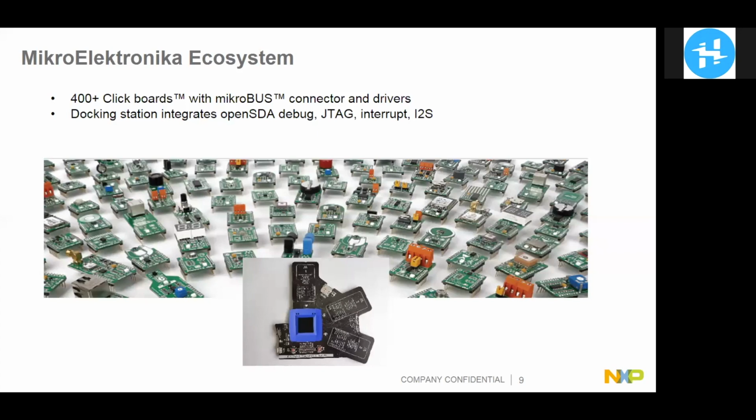And you can also add some security to your application. We have an NFC tag on board. So if you don't want to have this pairing process that occurs over the air when you connect your new device over Bluetooth or Thread, and there are some keys which are exchanged over the air at that time, you can use the NFC to exchange those keys at a short distance using contactless communication. So there are different mechanisms that can be implemented, and Rapid IoT embeds the hardware and the software to implement it.